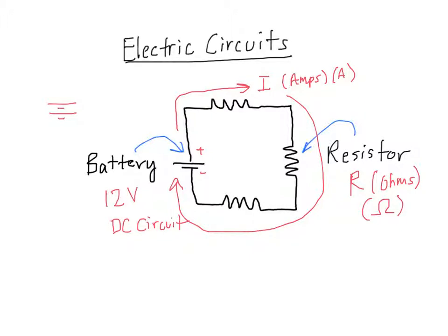Okay. And a battery is a source of energy. It's a source of power for the circuit to allow the current to flow. So it's basically like a pump in a piping system. I'm going to show you a little bit more complicated circuit to illustrate a point about how current flows through a circuit when it's got an option. Notice how here the current doesn't really have a choice of where to go. It's going to flow from the positive terminal to the negative terminal, following that convention I mentioned. And it doesn't have any other branches to go through.